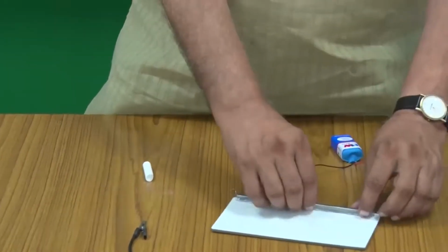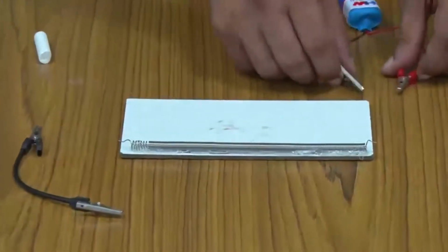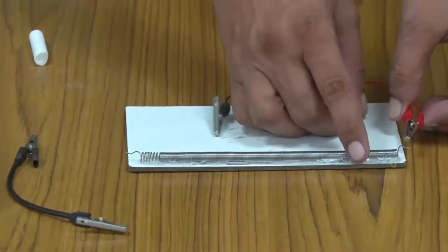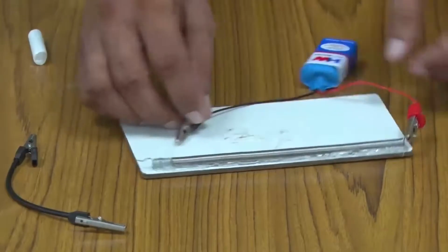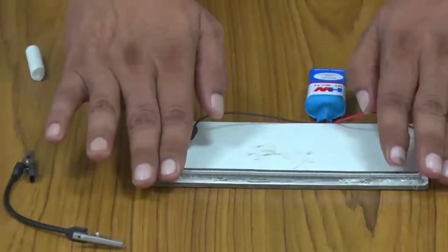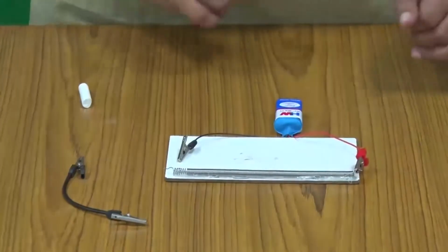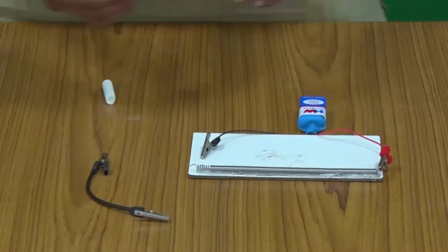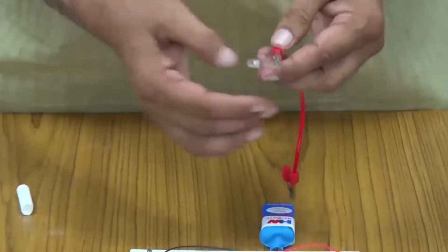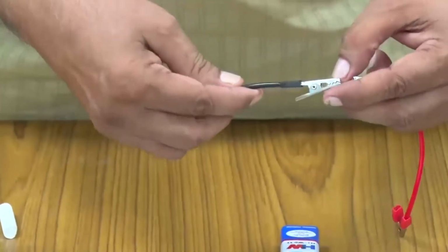So, what I am doing is I have taken this wire, this is a heater coil, and I will connect this battery at the ends of these two wires. The one I am connecting now and one I will connect when needed. So, this will go here. This whole 9 volt is dropped on this, and then I can take part of it, smaller voltages, from here. So, let me take the LED, and the longer leg I am connecting to this red connecting wire, and the shorter leg I am connecting to this black connecting wire.